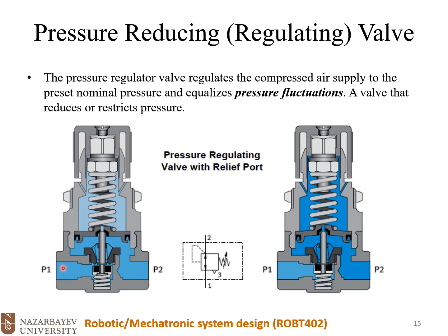And if the pressure is a bit lower than desired, the spring will push back, decrease the volume here, and increase the pressure. Of course, this spring is not designed to change the pressure significantly. It's not a compressor.